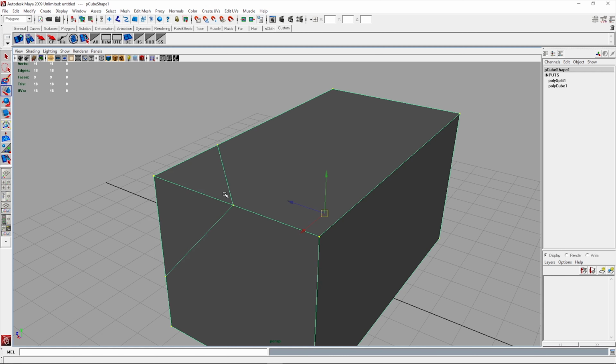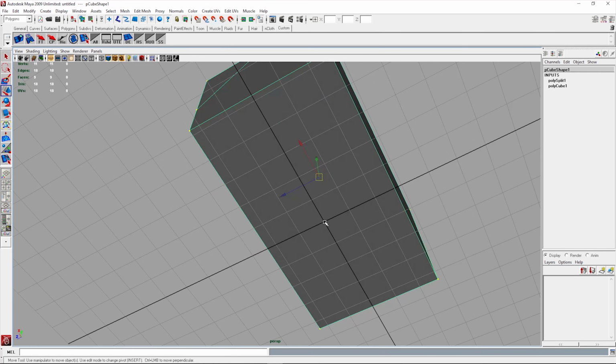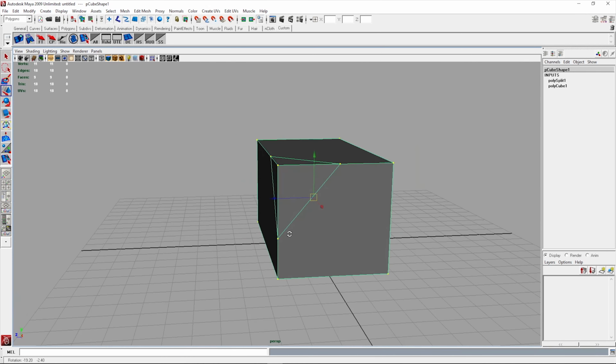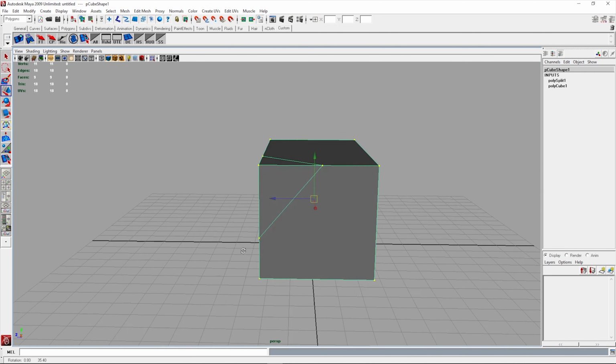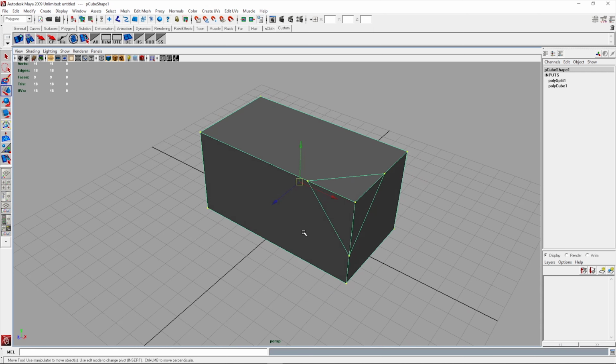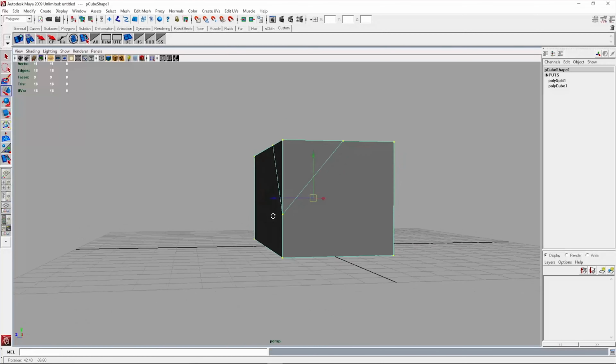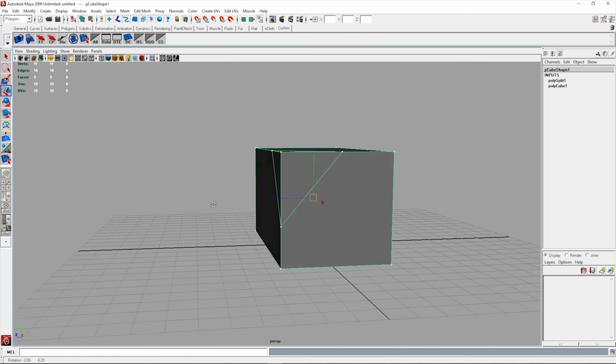Now, you can see these yellow points that define where all the edges meet. These are vertex points. And basically, the way the software package works is it defines these points with an XYZ coordinate based on this point of origin. So you can imagine we're probably moving 2.5 units, two and not quite a half units in negative X. We're moving up in positive Z. I can put the vertical panel on, but you don't really need it for now.